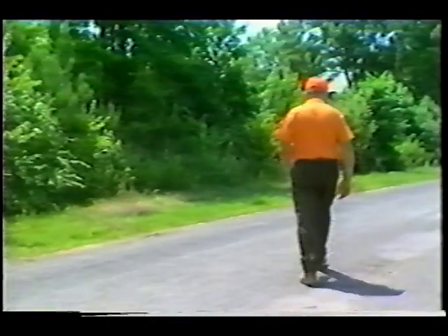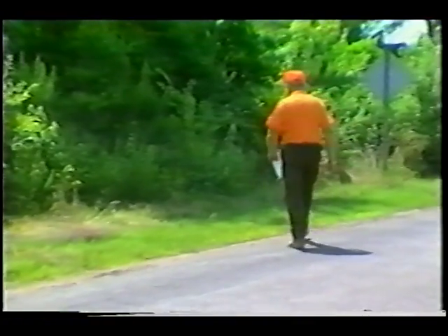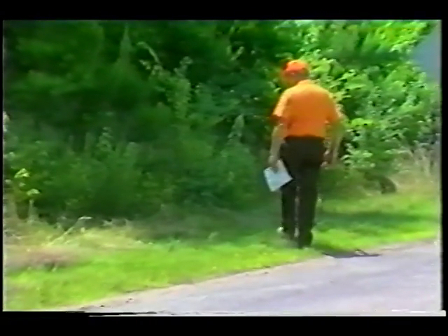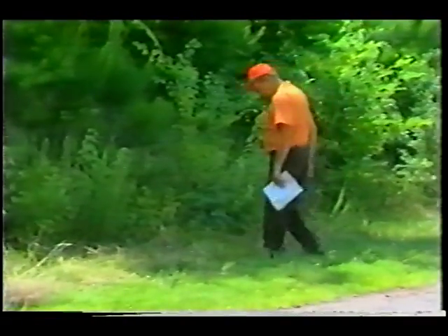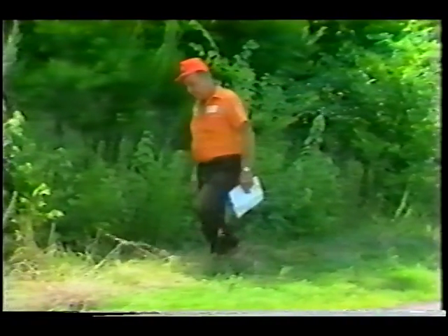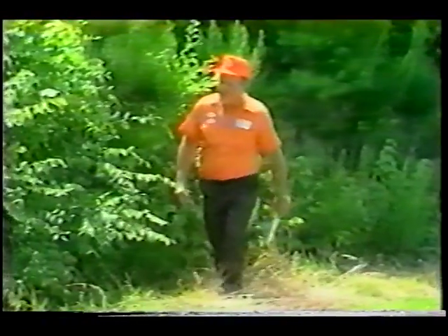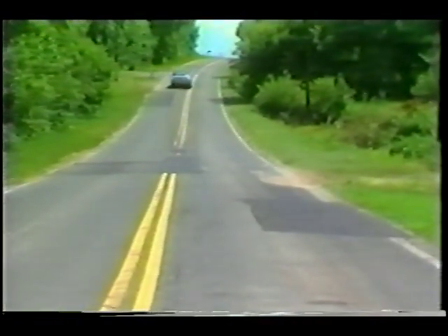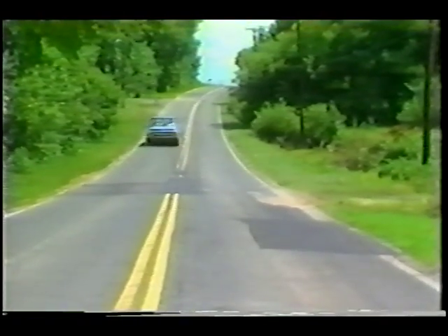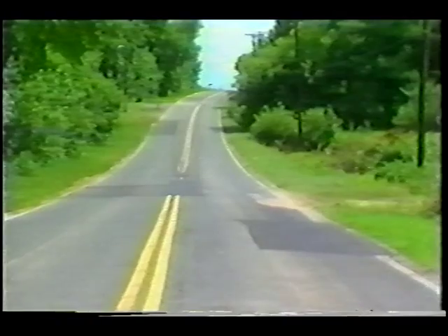Review drainage during the pavement examination. Many pavement distresses result from poor drainage. Look at the condition of ditches and other drainage areas to make sure they are open and at a level below the bottom of the subbase. The need for patching, leveling, or drainage repairs prior to a seal is evaluated during the existing pavement examination.